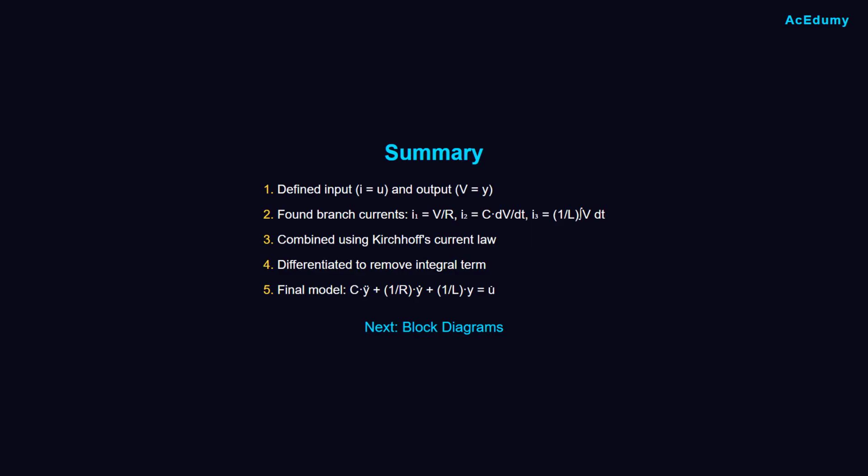Let's review what we accomplished. We defined the input current and output voltage. We found the current through each component using Ohm's law, capacitor equations, and inductor equations. We combined them using Kirchhoff's law, differentiated to remove the integral, and expressed the final model in standard control form.